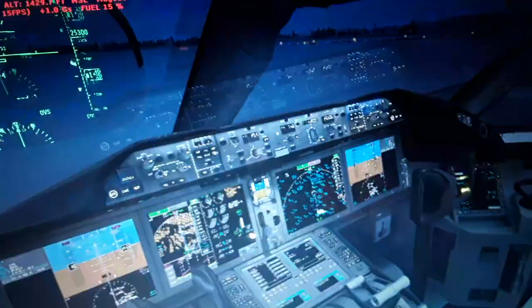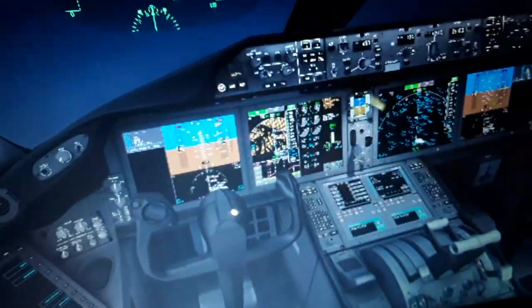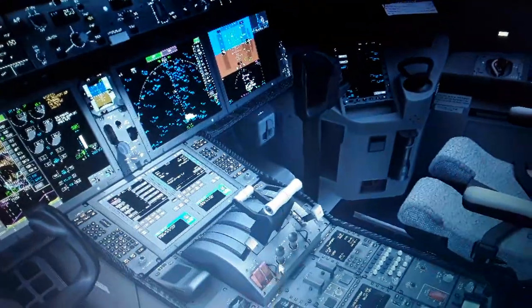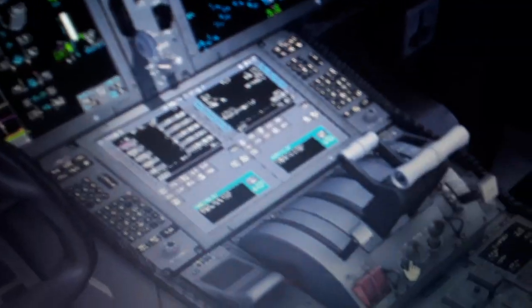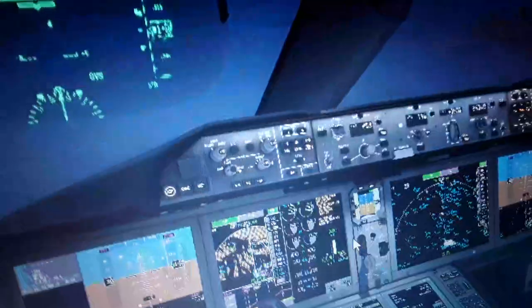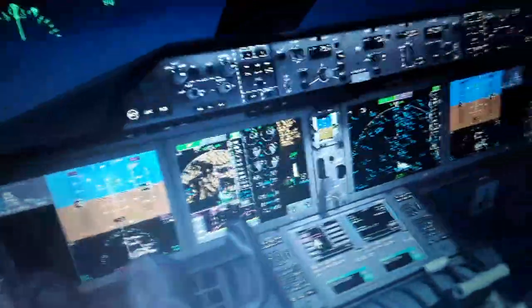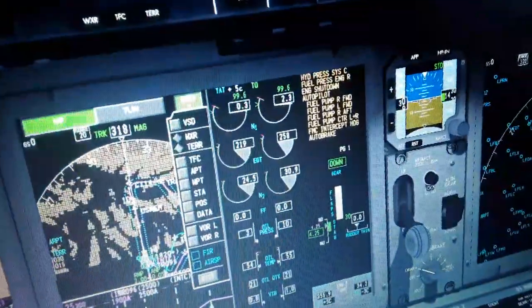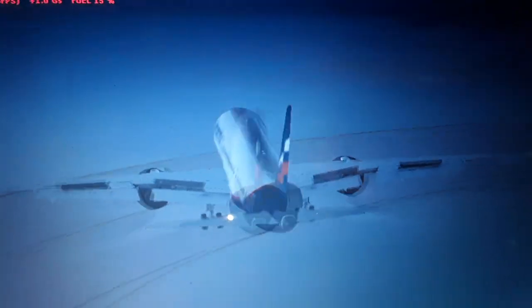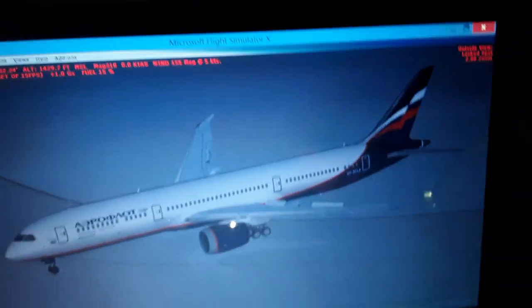We need to turn off both engines and restart them very quickly. So we turn off over here the fuel control, as you can see. So you'll see the engines indication, fuel control to the off position. We're gonna have some warnings coming up. I'm having the engines gonna stop like this. So we need to restart the engines.